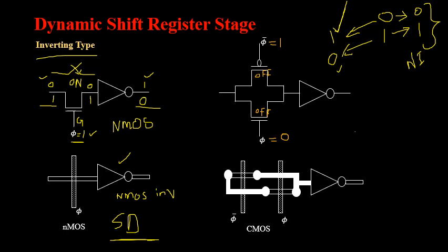When both the transistors are turned off, if I replace them with switches, this is an open switch. Even the NMOSFET is going to behave like an open switch itself. So whatever the data, whether I am applying a logical 0 state or logical 1 state, it is not finding any appropriate path either through the PMOSFET or through the NMOSFET in order to yield the output on the right side. So I cannot expect any sort of output over here. Usually we designate it as a high impedance or Z state. So now it is not showing me the exact behavior.